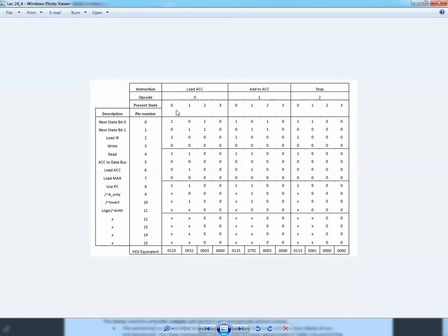But let's put this aside and let's talk about the efficiency of these instructions. If you look here, you'll find that we have 4 states. We are basically using one of them, while the remaining 3 are kind of wasted. So why don't we make it more efficient? Instead of ticking the clock here and then here and waiting, doing nothing in these 2 instructions,